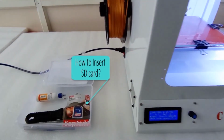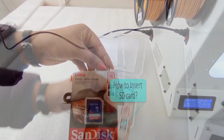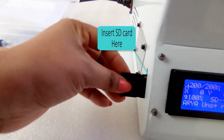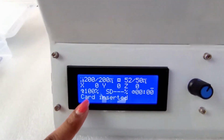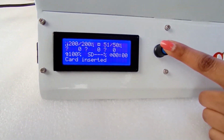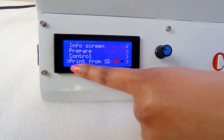Okay, how do you insert an SD card in the 3D printer? Insert the SD card in the given SD card slot. When you insert the card there, the LCD screen shows whether the card has been inserted or not. How do you give it the command to print? The SD card is already inserted in your 3D printer. Go to Print from SD card and give the print command.